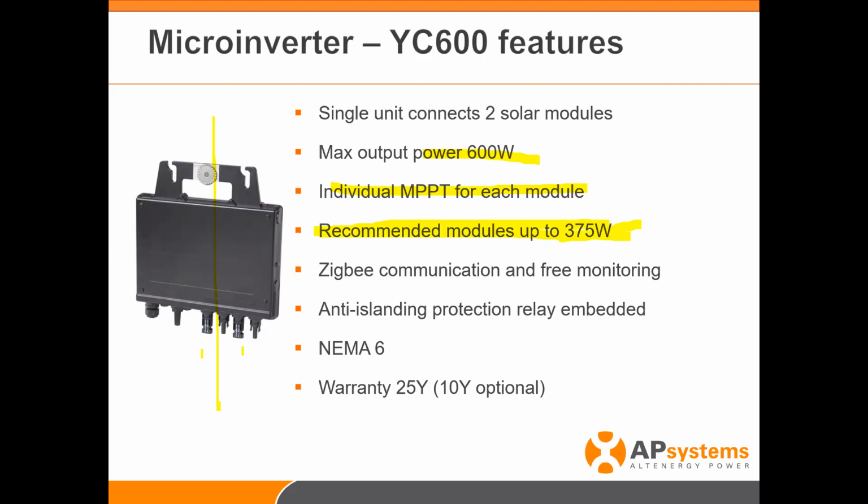This inverter will basically push out 300 AC watts per channel. And one thing that I definitely talk to a lot of customers about is what is the right size for my module? And it really comes down to the STC versus PTC of that module. I think it's important in the industry that we should talk about, and we'll talk about a lot more tomorrow as we get deeper into the specifications of this.